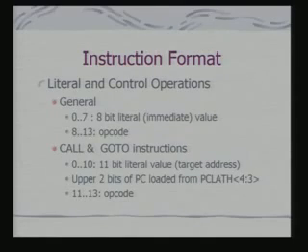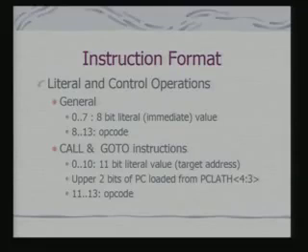Now, these literal values provide for immediate mode addressing, and the data used in the literal value is part of your program memory itself. It is interesting to note that your PC has 13 bits and your call and goto instructions have provision for specifying an 11-bit target address value.